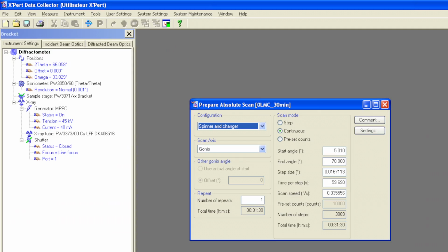The configuration of the XRD is mainly to optimize the X-ray beam to give the highest intensity and the required angular resolution. At the same time, beam overflow and scattering at low angle should be avoided. A range of 7 to 70 degrees 2 theta using copper radiation is usually enough to cover most of the peaks for cement-related samples.